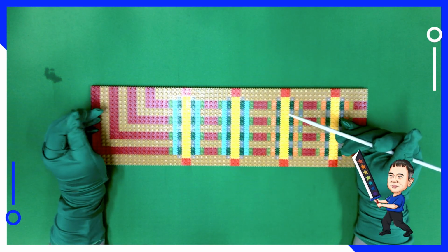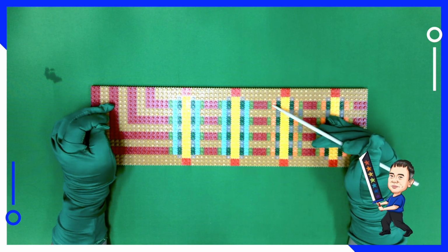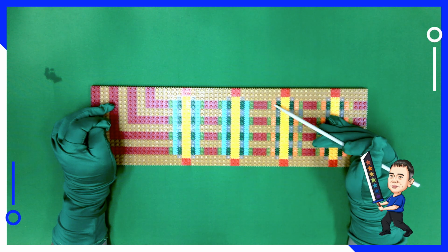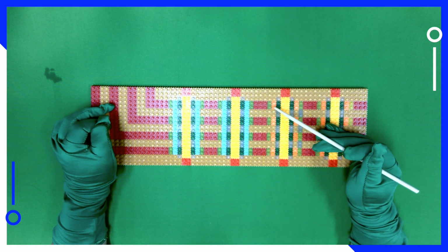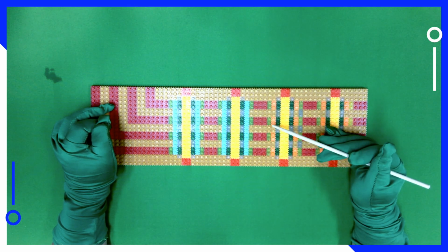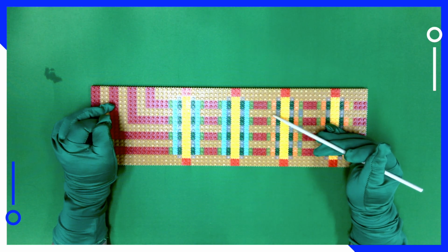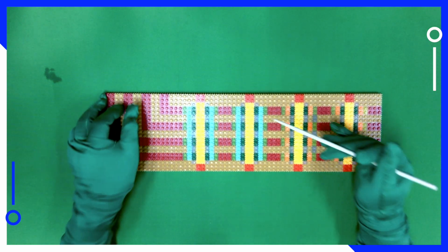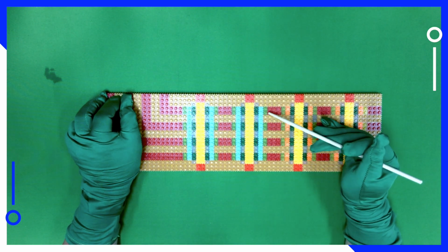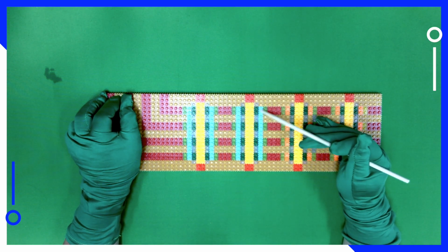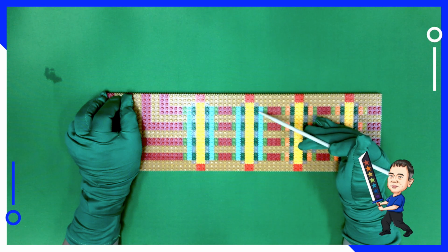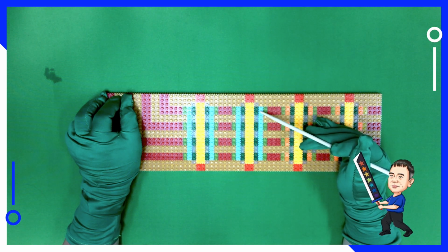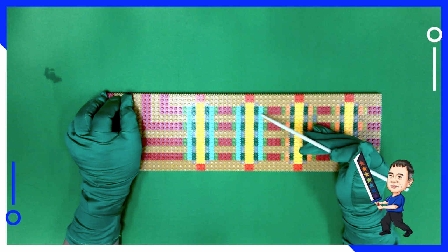Now, why do I have two different kinds? Well, the old floating gate is like this one. It's a conductor itself. So when you charge up or discharge, you charge up a conductor. But between the conductor and the conductor is the insulator, so the charge will not go from here to here. Another way to do it is using silicon nitride. So when you charge up, the charge will get trapped in the chemical bonds inside the silicon nitride, and it does not go from here to here.